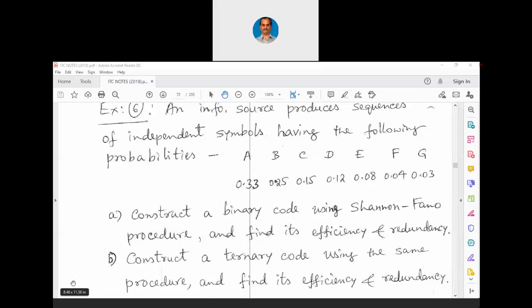We can have a ternary waveform there, which means we can have a waveform which is 0 volts, then 0.9 volts, then 1.8 volts. We can have it this way, where 0.9 volts will be VDD, and 1.8 volts will be 2 VDD, and 0 volts will be 0 volts. So, we can have waveforms which can represent more information with a lesser number of cycles. That way, we will have different types of waveforms.